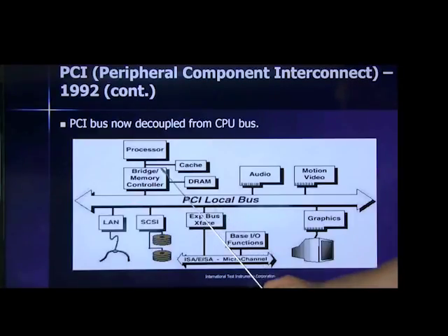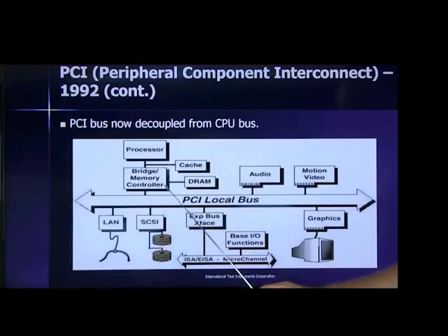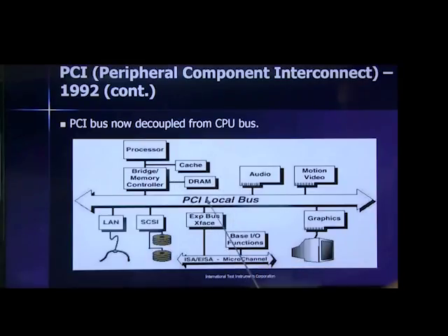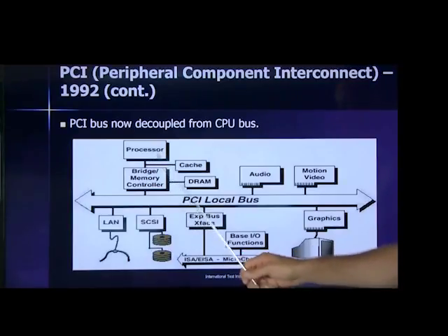Local buses should be attached to the processor, but it's a PCI bus. The way the bridge works is that the operating system configures the bridge to map a portion of the processor's address space to PCI address space. These two address spaces are completely separate.